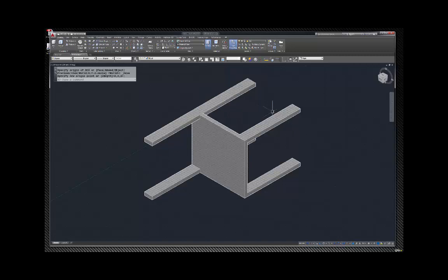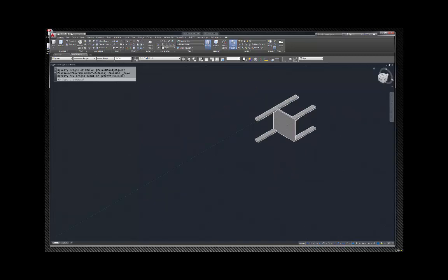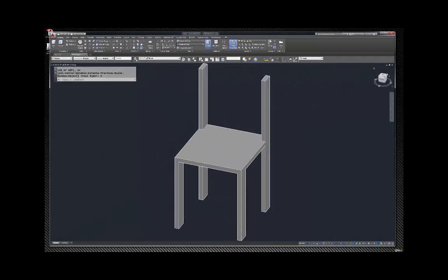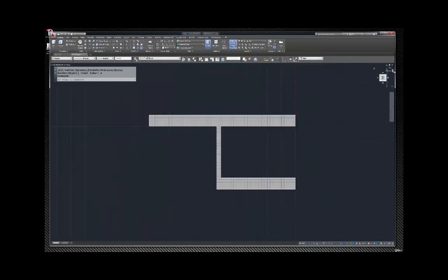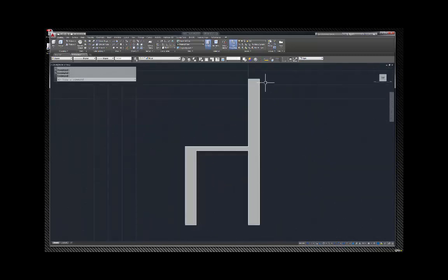it's now going across this plane here. Okay? If I go to world and stand this up, Z spacebar E spacebar, there we go, and go back to right, there you can see that the plane has moved to this edge. Okay? So I'm going to come around here, go here, and I am going to draw a line.